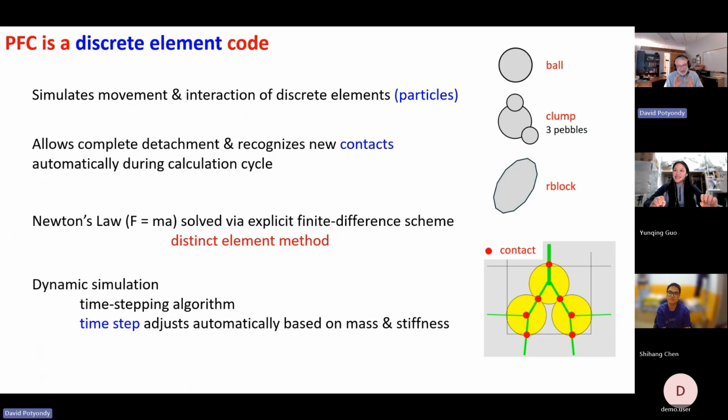So, okay, and it turns out, we're going to talk about this next time, that critical time step is going to be based on the actual system itself. It's going to be based on the mass and the stiffness throughout this whole system. Okay, and PFC, because it knows that, is going to continually keep monitoring the current state of the system, and it's going to keep adjusting the time step.